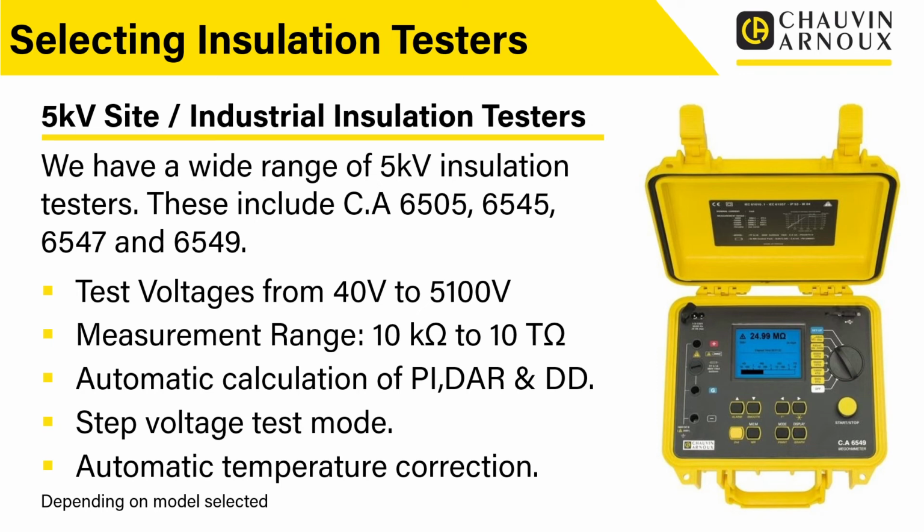But generally with these products, we've got test voltages, and usually the test voltages are selectable, anywhere between 40 volts all the way up to over 5,000 volts. And we've got a measurement range anywhere from 10 kilo ohms, so quite low in terms of insulation resistance, all the way up to 10 tera ohms, really, really high insulation resistances.